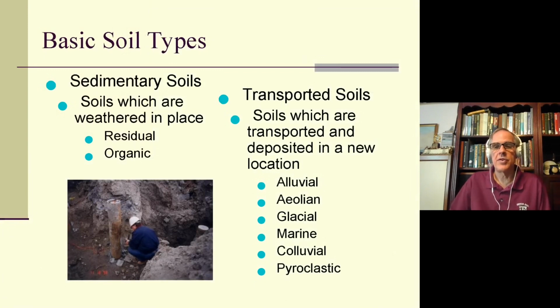With that, we're going to try to transition to basic soil types. There are sedimentary soils, which are weathered in place. They can be residual or organic. Organic soils generally are not so hot. They're good for agriculture. For decent agriculture, you have to have organic soils, topsoil, and that kind of thing. For foundations, no. Organic soils are the result of the decomposition of living material. That which has been in process of decomposing will probably decompose some more. So it's not really what you want to have in a foundation.